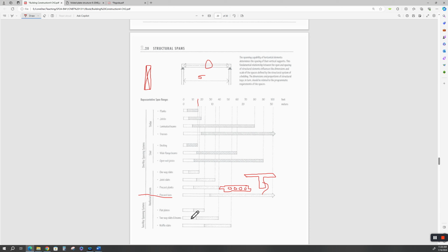They get pretty thick, and you got to have double layer of reinforcing steel in them, but you can do that. Now, if two-way slabs and beams, if you've got beams in there, then they can go up to 40 feet. That just means this is all one concrete deal. This is the concrete slab, and a section would have a beam box that would look like this.